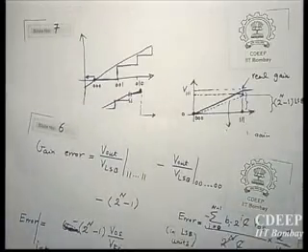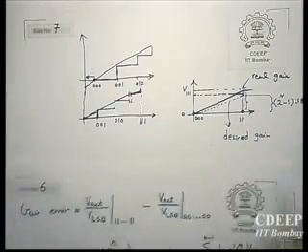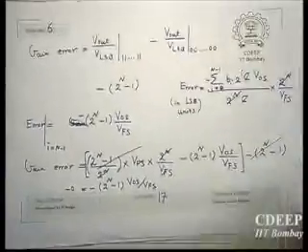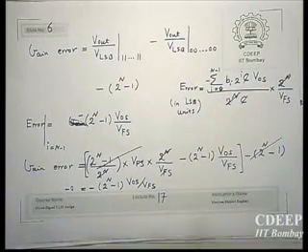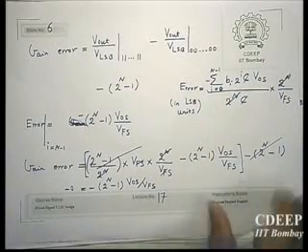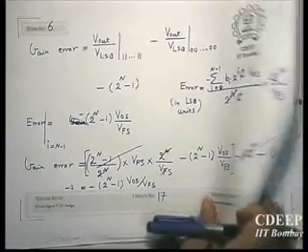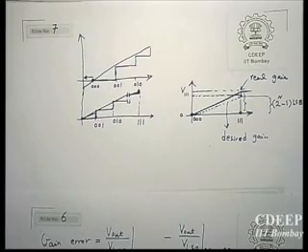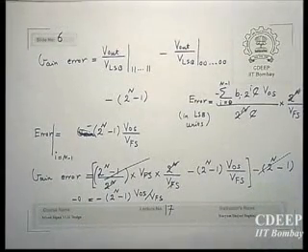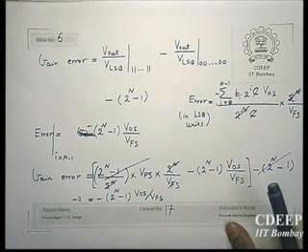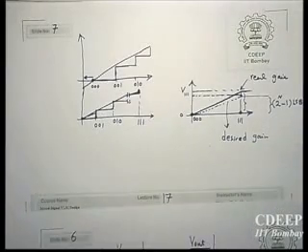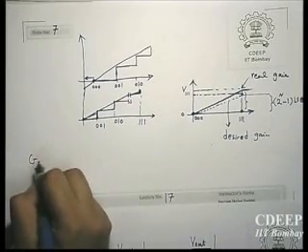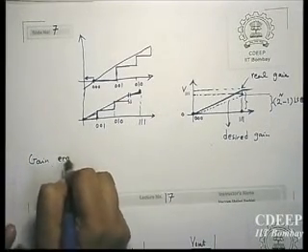But you can correct it easily because now you are scaling at all values, and interestingly your error also is getting scaled with the code. Therefore finally you will get a 0 gain error, and then you don't have any other. In fact, what I want to say is that the remaining effect of offset is only gain error. There is no distortion associated with it as long as offset remains constant. So therefore how do we compensate? So gain error compensation.